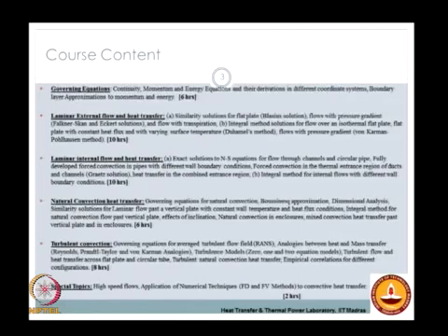That is, the velocity profiles remain invariant of the distance downstream, but there is a change in the thermal boundary layer. So that is your thermal entrance region of the ducts, and these are called the Graetz solutions. And of course, we'll also apply the approximate solutions to these problems.